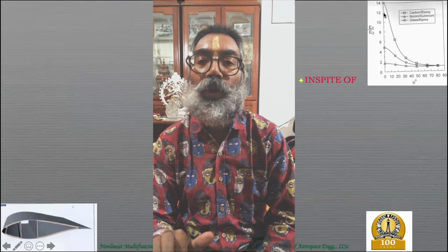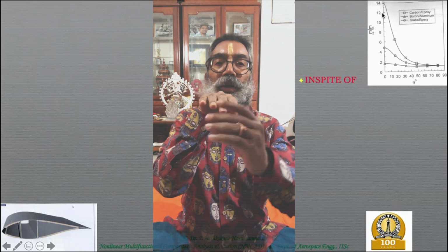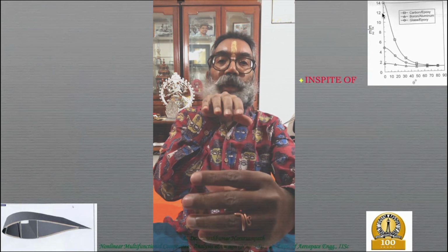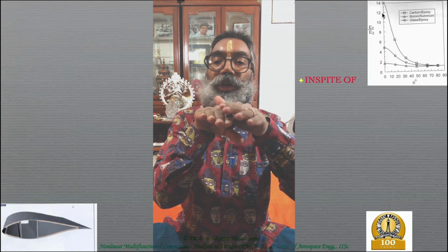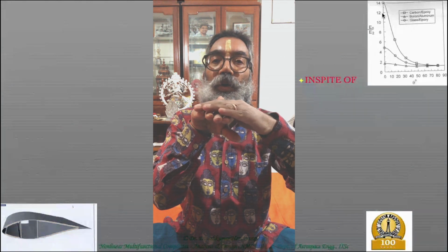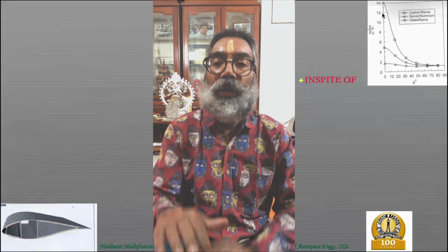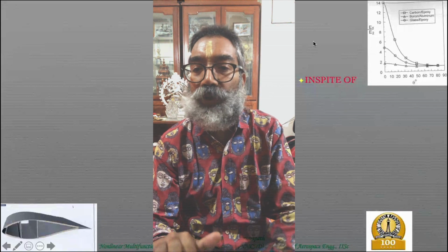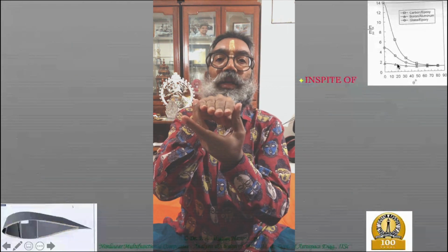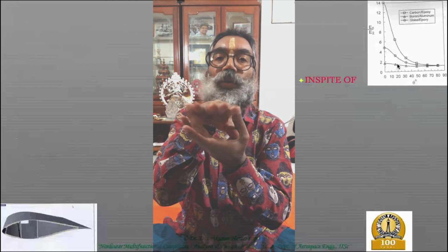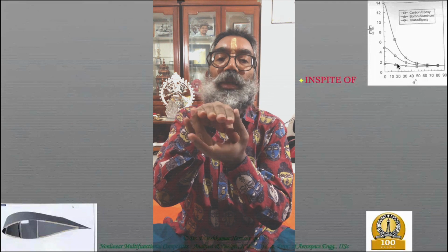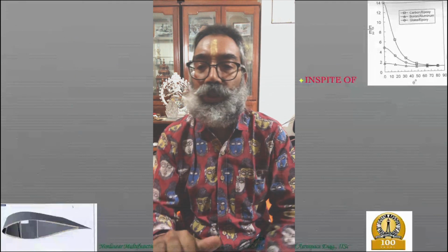But now if you go to directions where you're trying to load not along the fiber direction anymore, but at a certain angle to the fiber direction, obviously you're going to have a reduction, and the ultimate reduction will happen when you are having the load at 90 degrees, where the fibers hardly contribute anything towards the modulus, and it's only the matrix which contributes towards the modulus. So since we are dividing by E2, that is basically turning out to be 1.